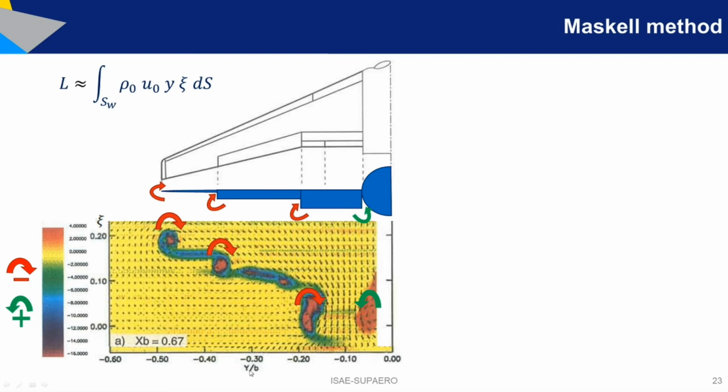So this will give me basically the lateral coordinate of a given vortex, and I have measured the vorticity at each one of the vortices. So basically I can compute the contribution of each one of these vortices to the lift, and based on that to reconstruct lift based only on the vorticity field. Let's go for it.